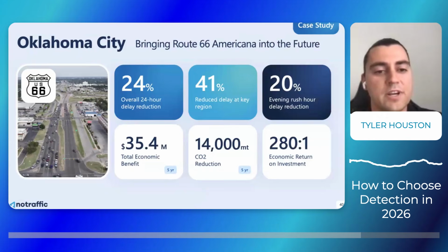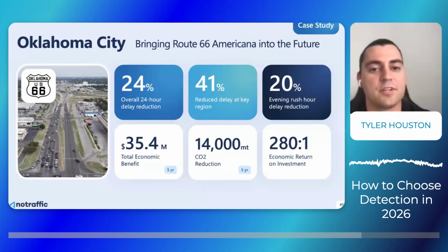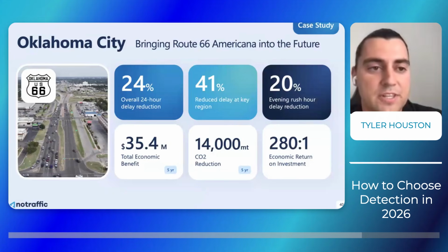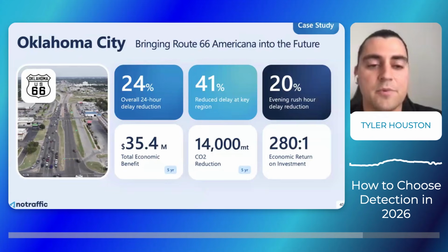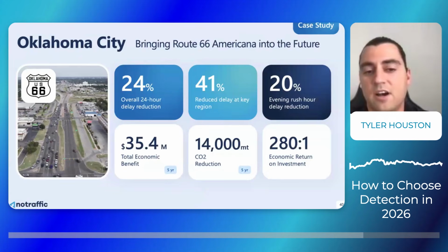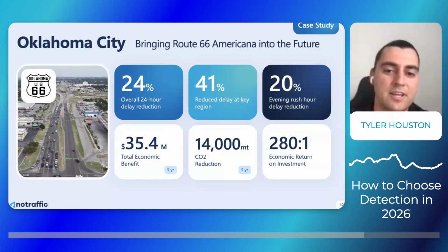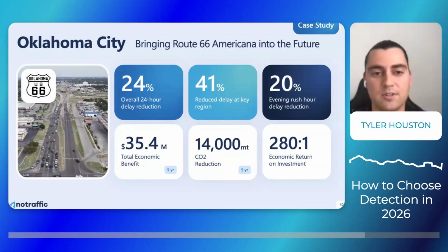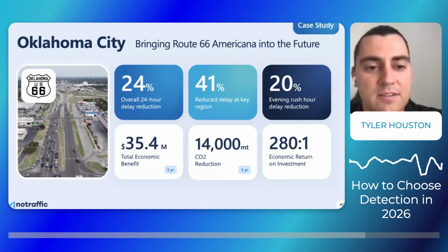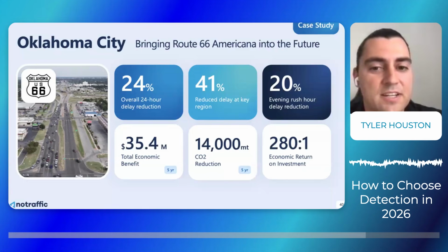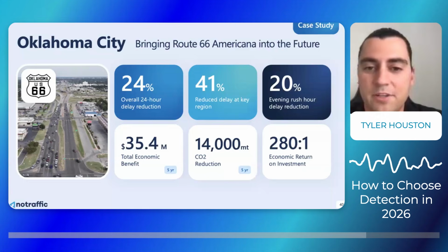We let the system run regular timing plans for about a month. During that time, we used the existing data that we collected from those intersections and did an offline model where we could create a calibrated existing condition model. We compared that to our optimization mode offline. We shared the results with the city, and then we went ahead and turned this on out in the field.